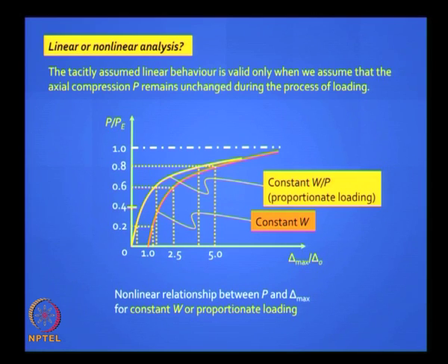If you are lucky, P is constant. If your P is constant, you can happily continue with your linear elastic analysis by adding some amplification. But if unfortunately P is changing, either you have a constant W case or a constant W by P case, then you have to recognize that you are dealing with a full blown non-linear analysis, which you can't do so easily. Okay, this is just for your information.